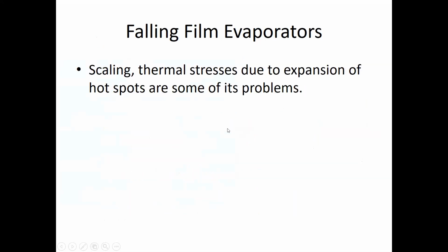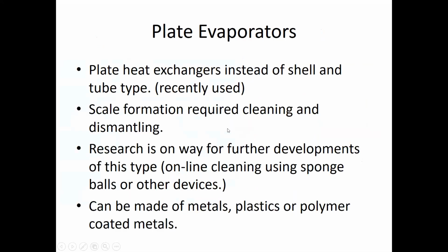So we're talking about here, this is a description of the difference between vertical and horizontal evaporators. They started lately to look at the plate and fin heat exchangers because the surface area is too high, and they said that we can make use of that for operation. The problem again is that if you have fin surfaces, eventually with time, corrosion can attack the surfaces and it becomes difficult to clean.